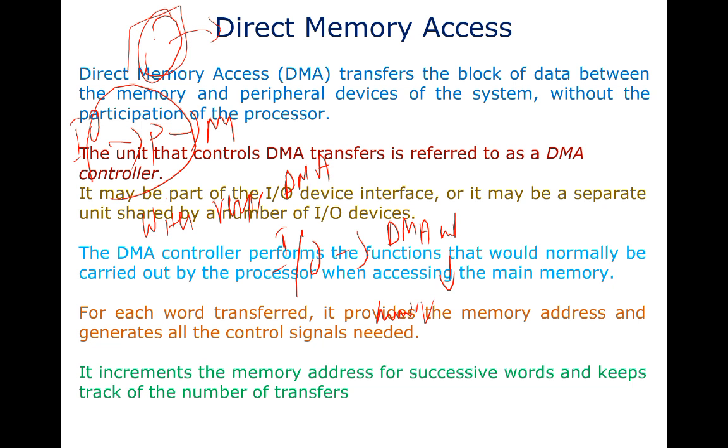Now, another thing to consider is why this DMA is required. The processor can provide the required transfer information to a DMA controller, and the DMA controller performs the actual transfer independently. DMA is particularly useful when a block transfer of data is required by a user or an application. Simply put, the block of data is the main criterion considered in DMA, and it is achieved using the DMA controller.